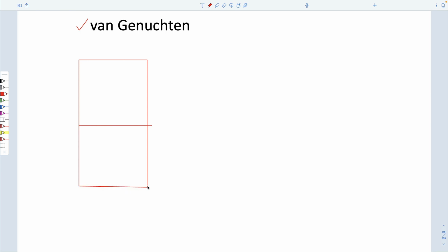What I was just saying was that if we look at these things around the water table, you know what these relationships look like. You've seen these many times. They're the inverse of each other. This is capillary pressure, which is related to elevation. This is saturation of water between 0 and 1.